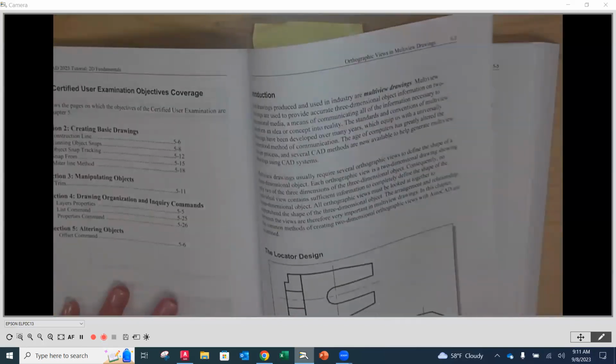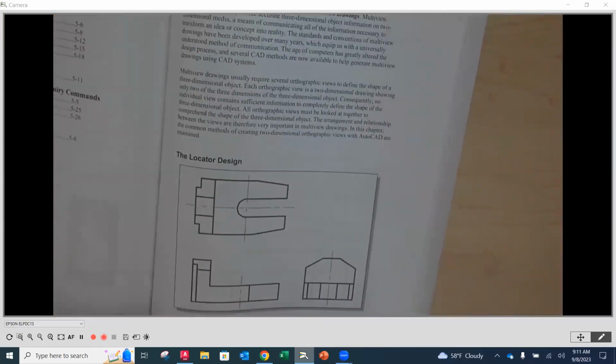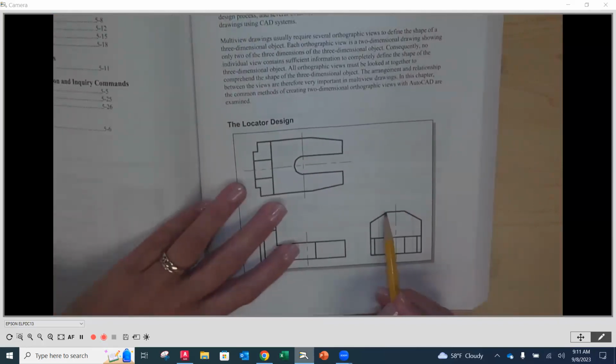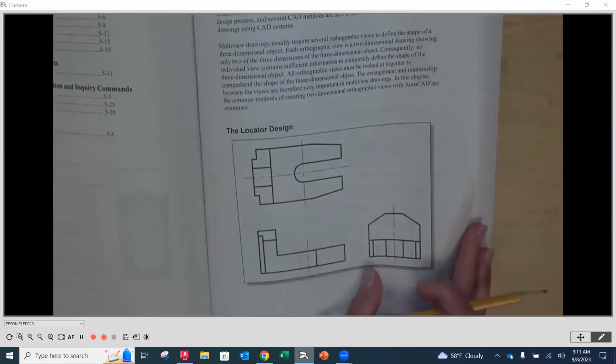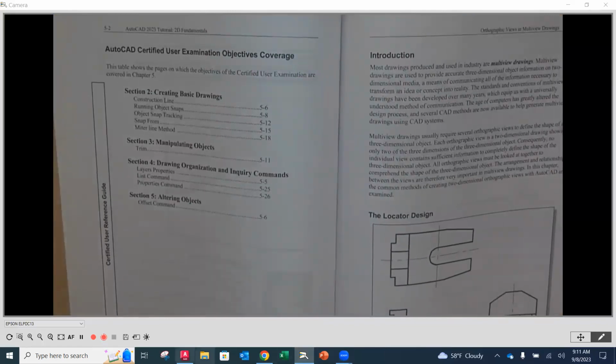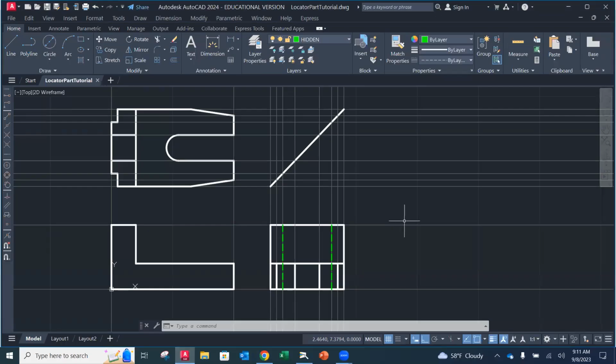So if we look back at our right side view, from horizontal, this is going to be 30 degrees. From horizontal, this is going to be 30 degrees. So we need to get this angle in there. All right. So that's what we're going to do in AutoCAD next. Okay. So what I'm going to do is draw a horizontal line, and I'm going to extend it further than I need it to be. And then I'm going to rotate it, and then we're going to trim away what we don't need.